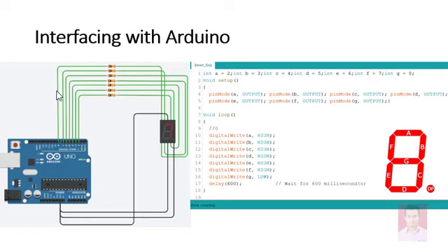On this, if a high signal is sent, a particular LED segment will turn on, and the segment which will get 0 will be turned off. Like this, you can go on and generate the characters. I have written the program for each character separately. So this code is to display 0. Void loop is going to display the character continuously.